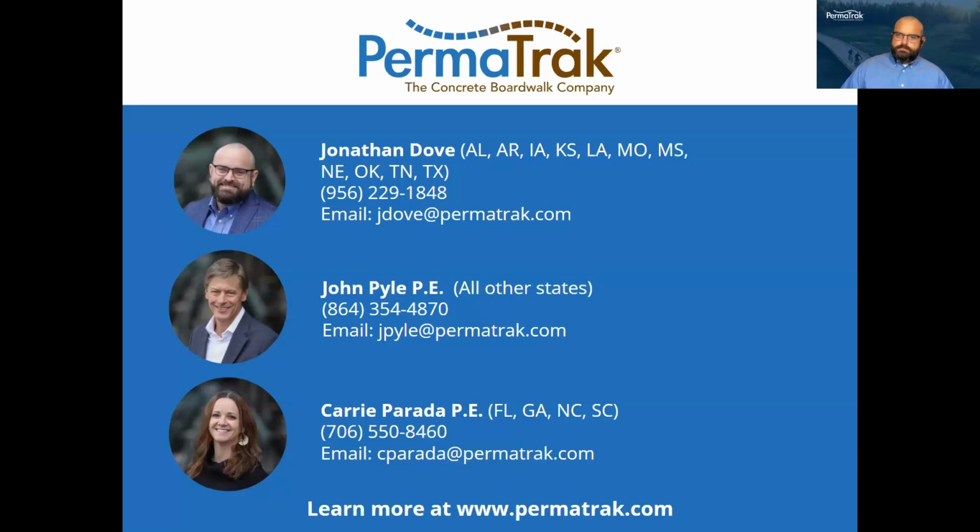The beams themselves, we have 2 different beam series there. We have a small beam series, which would simply be 9.5 inches tall. Our medium beam series is 14 inches tall. And then, of course, when we get larger than, say, 24 feet, the beam depth and width becomes a custom beam that, again, our forms are flexible where they can be accommodated to span those distances. And we've gone as large as 50-foot spans, but the thickness may be 27 inches thick for something like that.